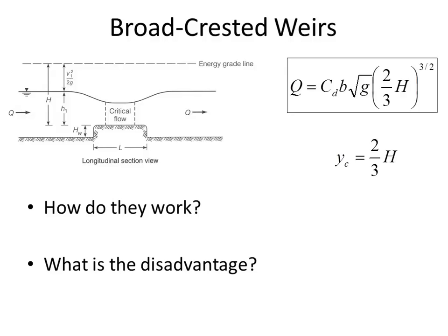And so you can know the flow rate in the channel by simply knowing the width of the channel and then knowing how much specific energy there is. Well, how much specific energy is there? It's a function of the critical depth, which is what you're measuring over that broad-crested weir. And you can calculate the coefficient of discharge by the ratio of the height of the weir to the specific energy. So H versus H sub W goes into there, but a typical value is about 0.62.